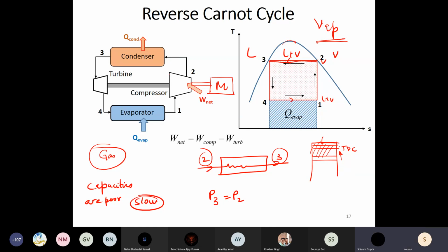So there would be an enormous increase in the pressure, and this liquid water will either break away those intake and discharge valves, or it will come out of the sealings between the piston and the cylinder. So there would be a catastrophic failure in case you fill liquid into a device that was designed for vapor or gas.